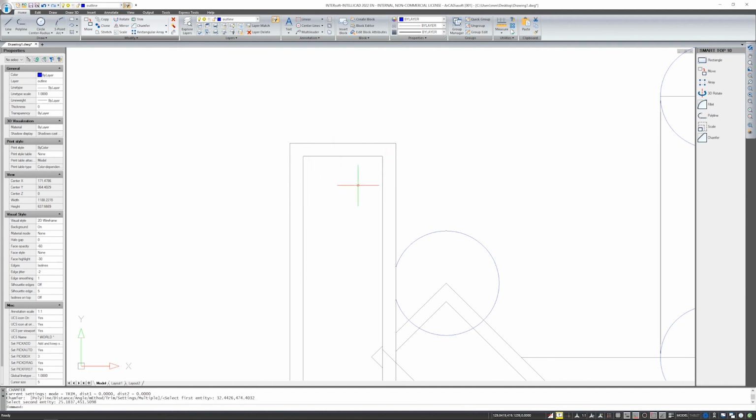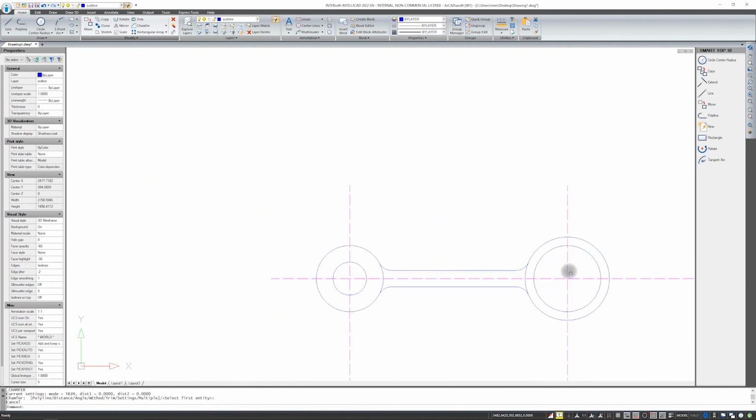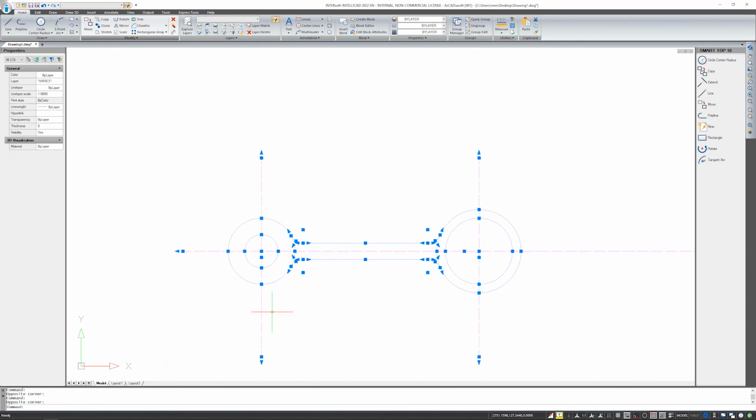So I do not have to enter the cut option several times and show these individual elements separately to be cut. So chamfer can cut corners and, for example, lengthen or shorten, as long as you have properly defined the settings. When you draw, a function that is frequently used is rotate. I select the elements that I want to modify. With the right button, I choose rotate.